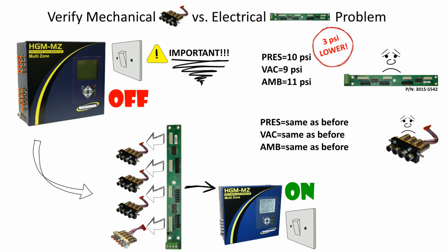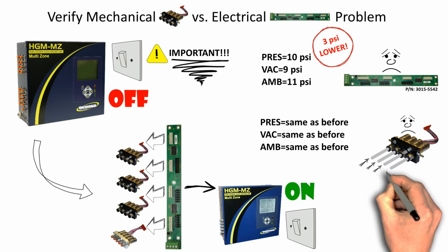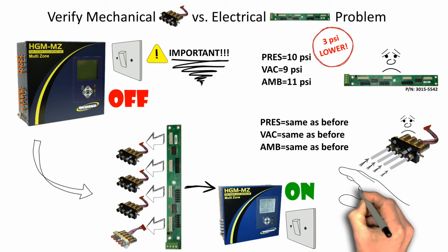You can confirm this by feeling for air leaks along the external sample line connectors. You can use a flow gauge if you have one, or just move your finger along the connectors and feel for an airflow. It may be difficult to feel airflow from a stuck solenoid directly against the quick release zone connectors, so try adding a small length of sample tubing and checking the flow from the end of the sample tubing. It actually makes it easier to detect these types of leaks.